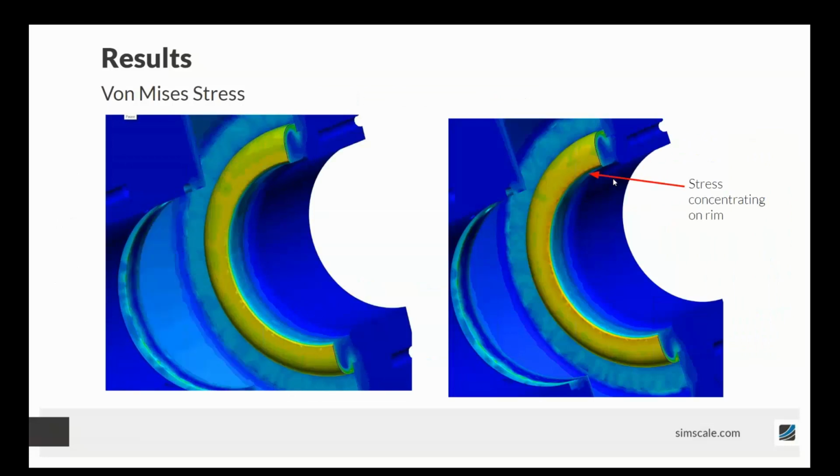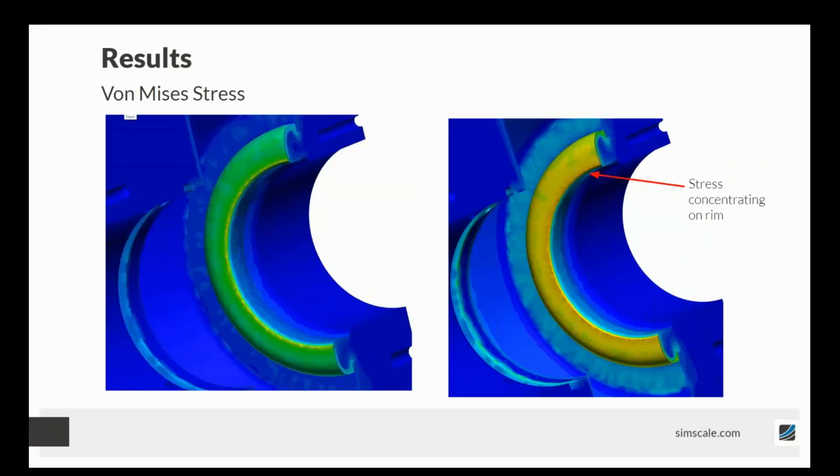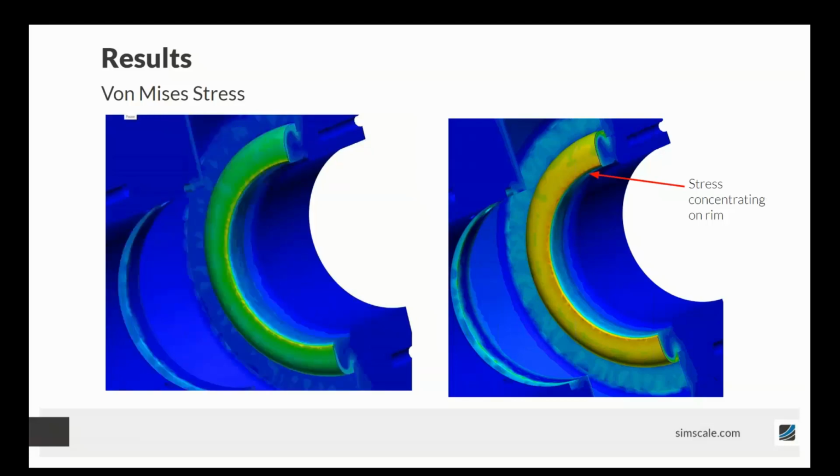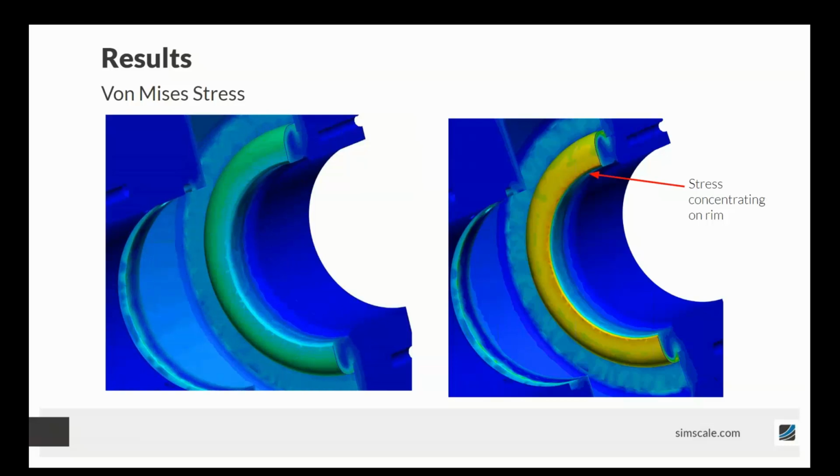Now, if we want to have a look at the mechanical stresses, it's important to find the areas in which the stresses are concentrating. During that combustion, up until 0.1 seconds, not only are we getting that applied pressure, but we're also getting the mechanical stress induced by the thermal shock. That goes for after the thermal shock as well, but at the end of that thermal shock is the point where we're going to have the highest level of mechanical stress.